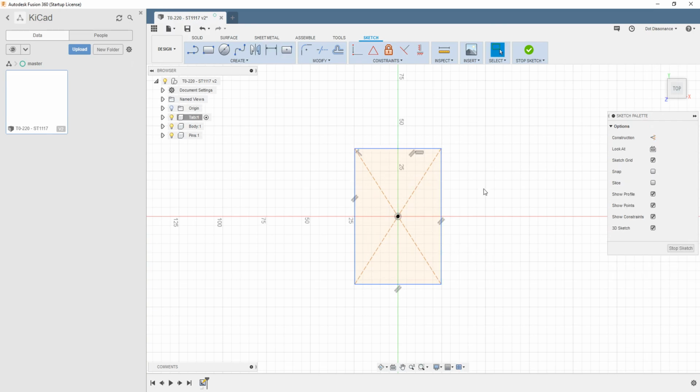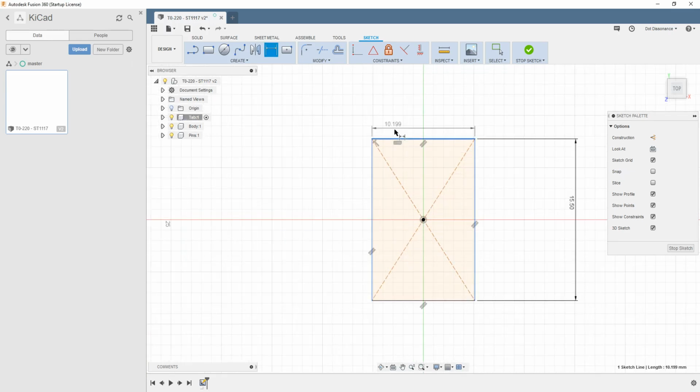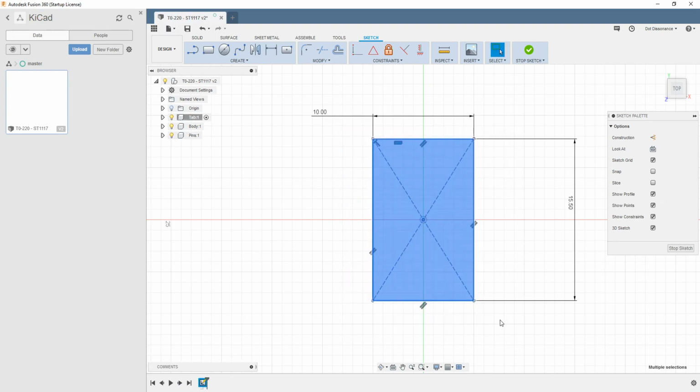I'm going to make this about as big as the part is. So it's about 15.5, 16 or so millimeters tall. And it's about 10 wide. And I probably should have turned on construction element before I started there, but oh well. We'll go like this. We'll hit that or hit the X.